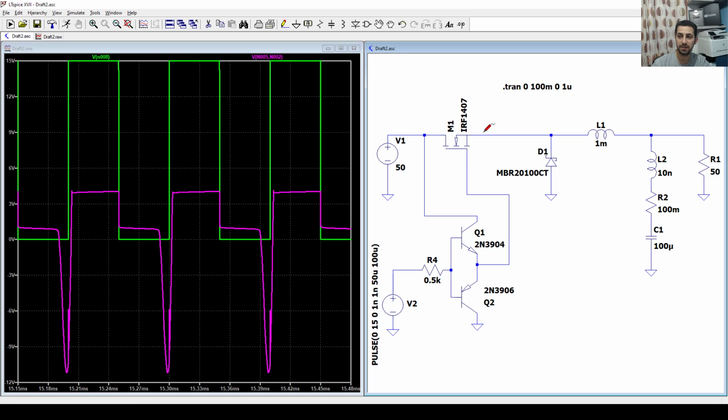So the voltage there, once this turns on, will be close to that one. So from where will you get more voltage, by 10 or 20, to be applied on the gate? That drives us to use something called a Bootstrap Capacitor. What is a Bootstrap Capacitor? The Bootstrap idea is to have a capacitor like this, and that capacitor is referenced to the source. I will put it like that, and I will make one point here connected to the source.